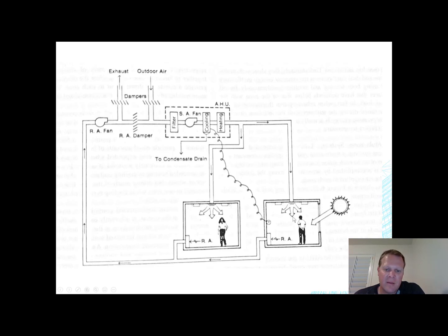So this office is going to need more cooling, and that's where the thermostat is. But this room is getting the same amount of cooling as this room, and there's less heat gain in this room. So this room is literally going to be colder, because it's calling for the same amount of cooling where there's no sun to heat up this office.